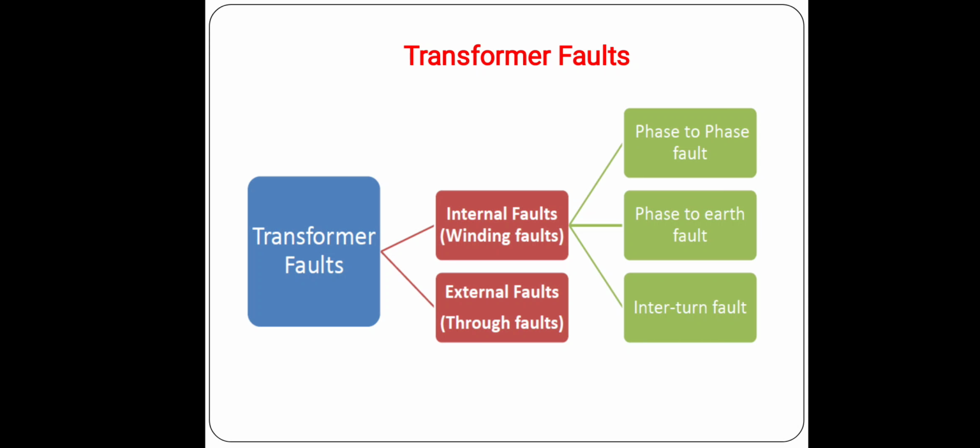Basically, phase-to-phase short circuits are most frequent on leads of three-phase transformers, while the interphase short circuits, that is also known as phase-to-phase short circuits, within the windings are less frequent. Earth faults and inter-turn faults have the highest probability on the power transformers.